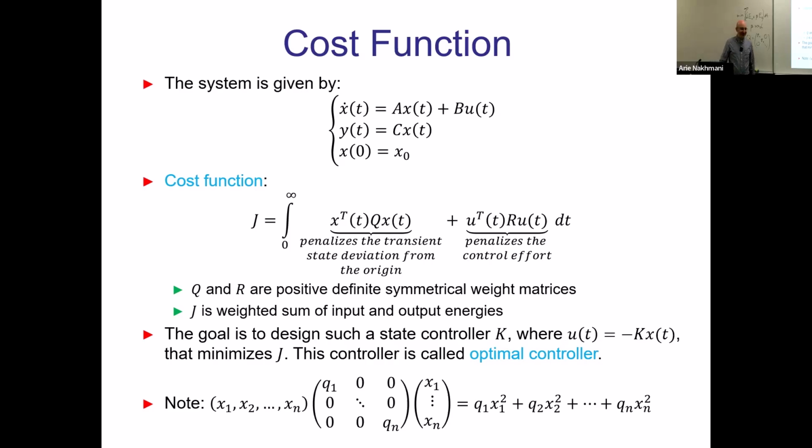Yes. Basically, you have removed half of the constraints, like for example, from Q and R. If instead of considering all the possible values, now we will be considering only a few values of Q and R. Well, not really, because the Q matrix is n by n. Even for SISO systems, you have n squared values to choose plus R, which is n squared plus 1 values to choose. And in poles, you need to choose typically only half of them or close to half of them, right? Because if some of them are real, you put them on the real axis. If they are imaginary, you have pairs which are exactly the same conjugate values, right? So you actually need to figure out more numbers here than before.